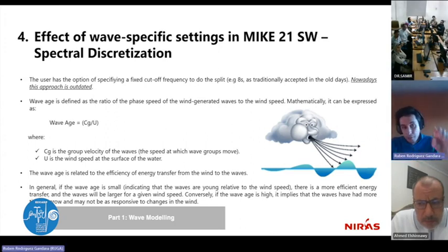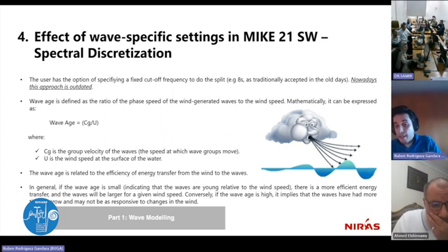And if you remember the transport equation, on the left hand you had how the energy moves within the domain, and on the right hand you have the sink and source terms. In the sink and source terms, you don't have any source. You don't have wind to keep those waves growing or traveling. You only have dissipation by friction, dissipation by steepness, dissipation by breaking. And what happened? After a few time steps, that wave condition or boundary condition that you were imposing at the boundary will decay and die.